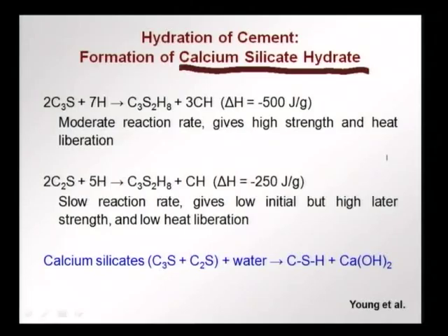There is a tendency nowadays to have cements with higher C3S content, so that we get earlier strength gain. This means that we are producing more heat, which can lead to cracking if not cured properly and taken into account in the early stages.